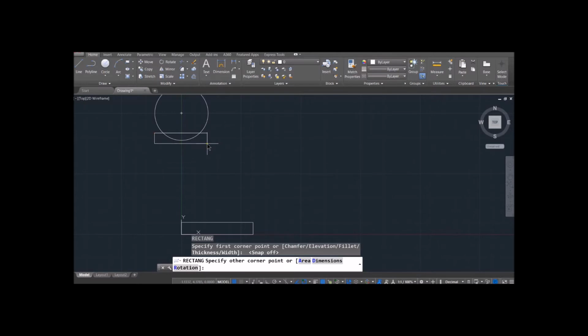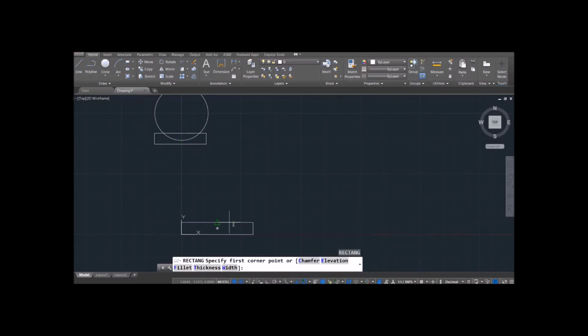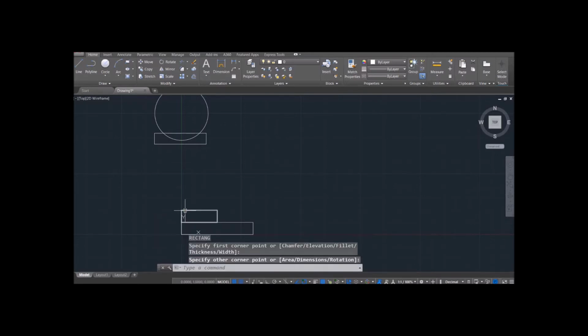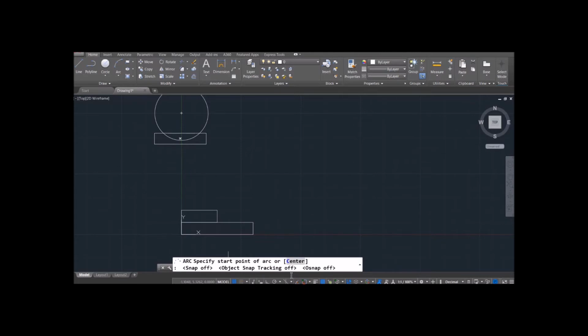So I'm actually going to turn off some snapping tools here and just eyeball this thing. And for something like a chess pawn, that doesn't have to be exact. Remember, there's a couple different snapping tools. There's snap to your grid, and then there's also snap to objects. So play around with those snapping tools and get real comfortable using all those 2D drawing tools. Let's see here. If you hit the arrow, you can see what you're snapped to, and then clicking on the objects, if they're not blue, it's off. So I just turn the snap off.